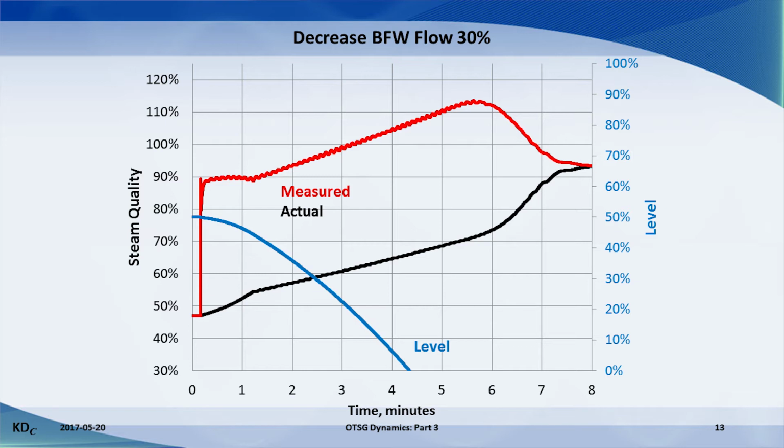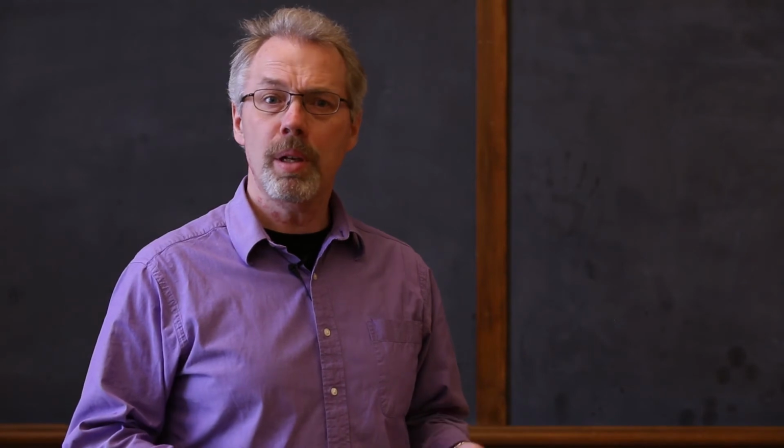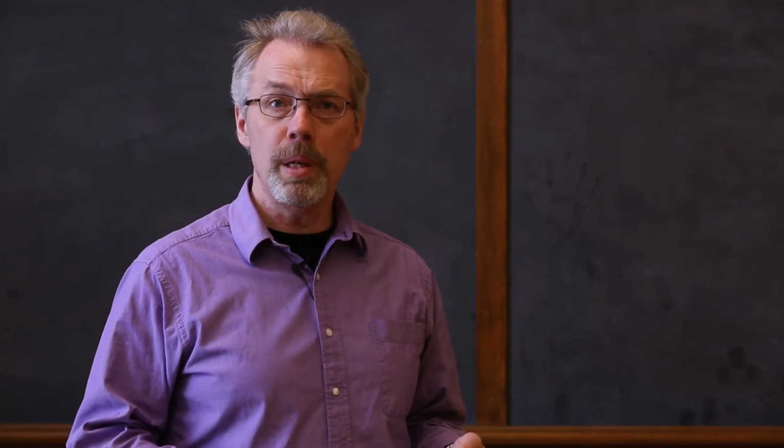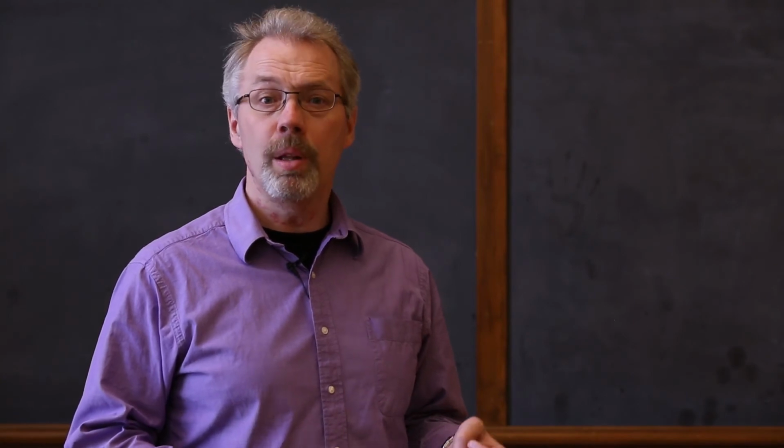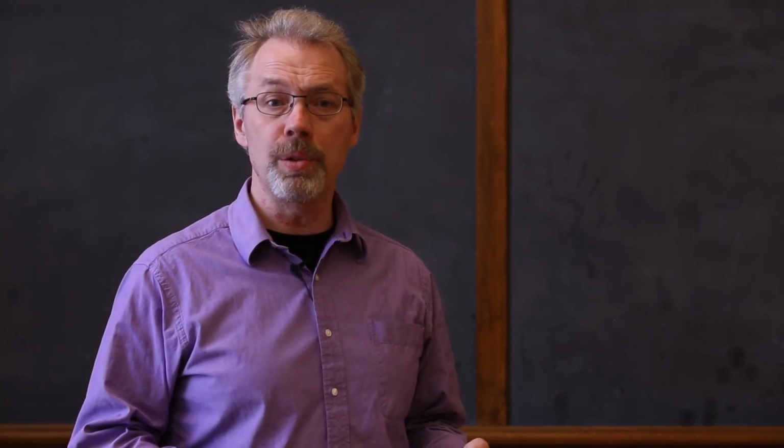The best indication of what is really happening is the level in the steam separator, the blue line. This is provided that the level controller is tuned slowly. The level slowly drops off rather than seeing a sharp change in slope. A sudden drop in the boiler feed water flow rate looks a lot more serious than it really is. In the long term, there will be the inevitable increase in steam quality. But in the short term, the Venturi steam quality reads false and overstates the steam quality.